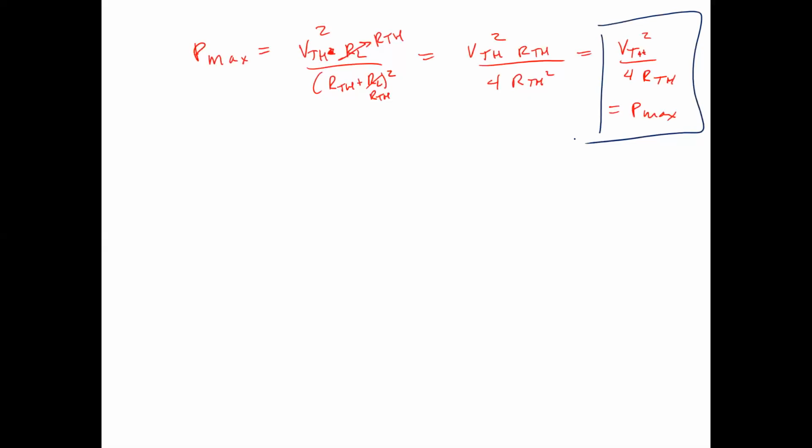If there are dependent sources, you have to turn off the independent sources and leave the dependent sources on. You have to do nodal and mesh analysis maybe to find the open circuit voltage, short circuit current, all that stuff, or hook up a test source. You see how complicated this is? This is actually a much higher level problem. You have to switch in all these high level tools to get to this answer, which is going to require maybe a couple pages of work to find.